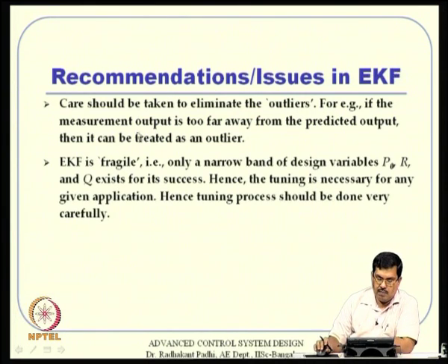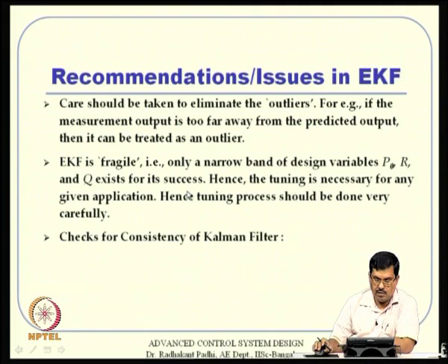Also remember that EKF in general is fragile, that means only a narrow band of design variables will be very good for successful operation. So, do not lose your patience. Keep on tuning this, and ultimately you will see that EKF works wonderfully for a number of problems, but you need to have patience for making it operational.